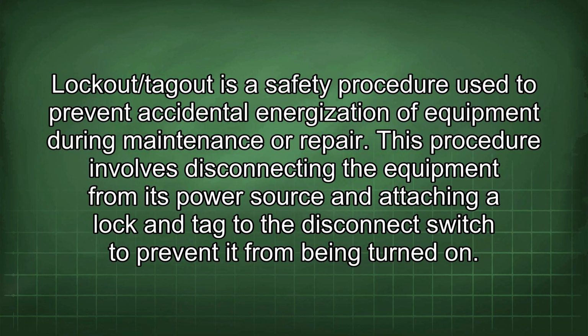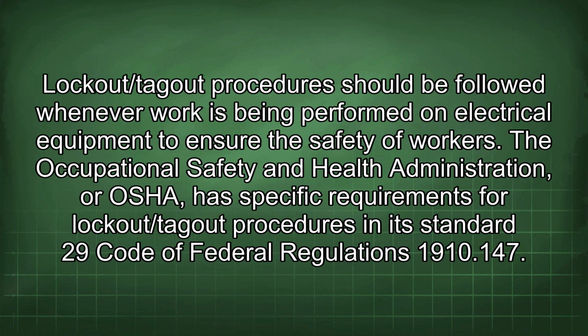Lockout/tagout is a safety procedure used to prevent accidental energization of equipment during maintenance or repair. This procedure involves disconnecting the equipment from its power source and attaching a lock and tag to the disconnect switch to prevent it from being turned on. Lockout/tagout procedures should be followed whenever work is being performed on electrical equipment to ensure the safety of workers.